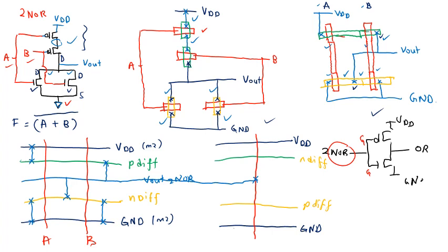And then I think it's better to put the other side, this side. Okay, VDD to the N diffusion, this part. And then we have the N diffusion connected to the output, this is our output, the drain side, and this one is connected also to this side, and you have this part connected, right? So this is your output. Is it clear? I hope so. Okay, so this is how we do it using the stick diagram.